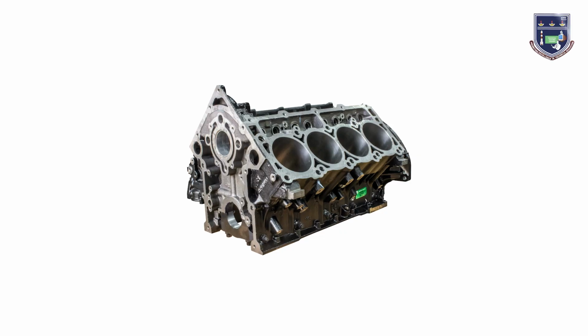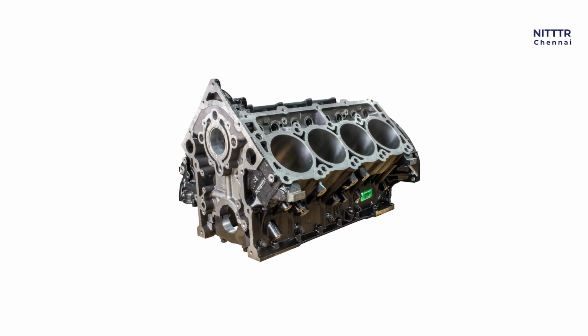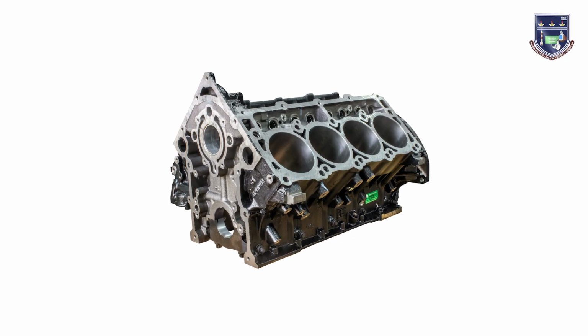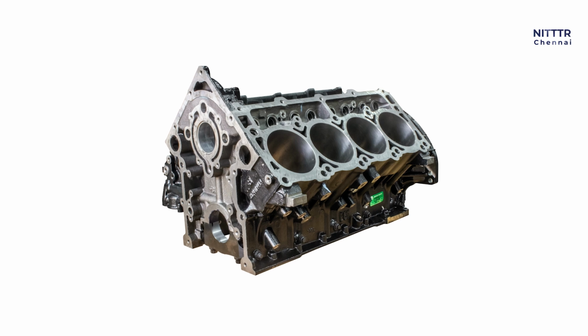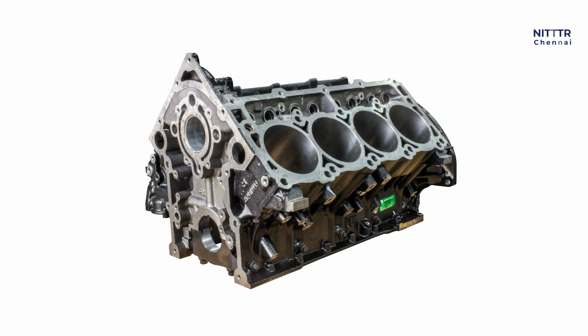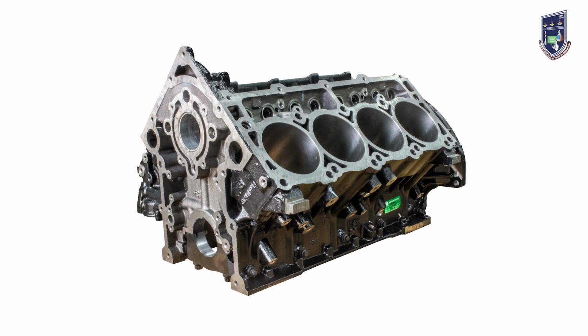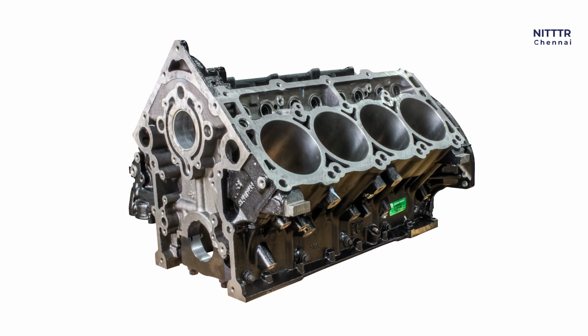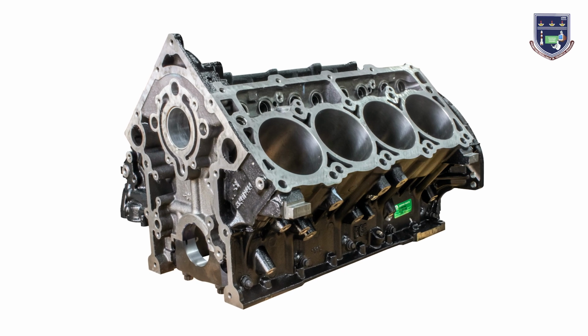It also influences the tool selection, cutting parameters, and process sequencing to ensure an efficient workflow. For example, consider a cast iron engine block. If the originating operation is casting, the process engineer must account for casting defects, stock allowances, and rough surface texture while planning the subsequent machining steps.